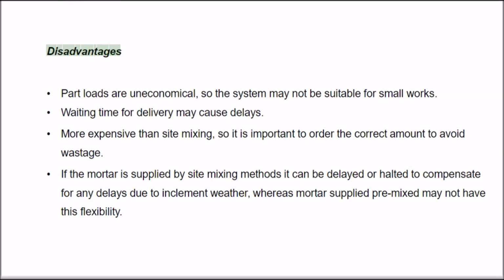Disadvantages: part loads are uneconomical, so the system may not be suitable for small works. Waiting time for delivery may cause delays. More expensive than site mixing, so it is important to order the correct amount to avoid wastage. If the mortar is supplied by site mixing methods, it can be delayed or halted to compensate for any delays due to inclement weather, whereas mortar supplied pre-mixed may not have this flexibility.